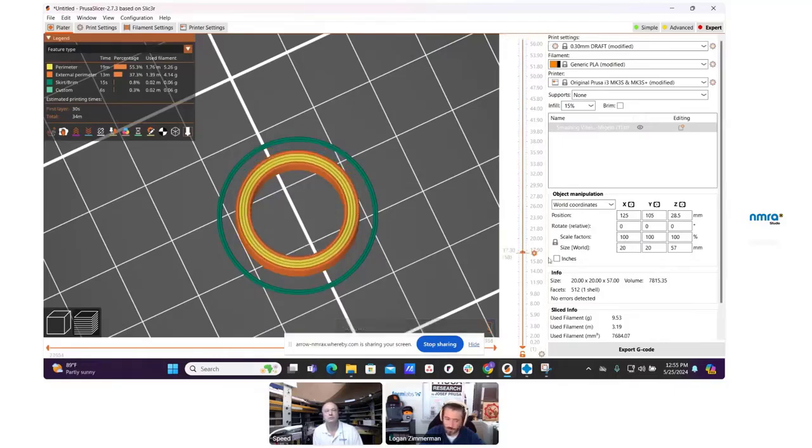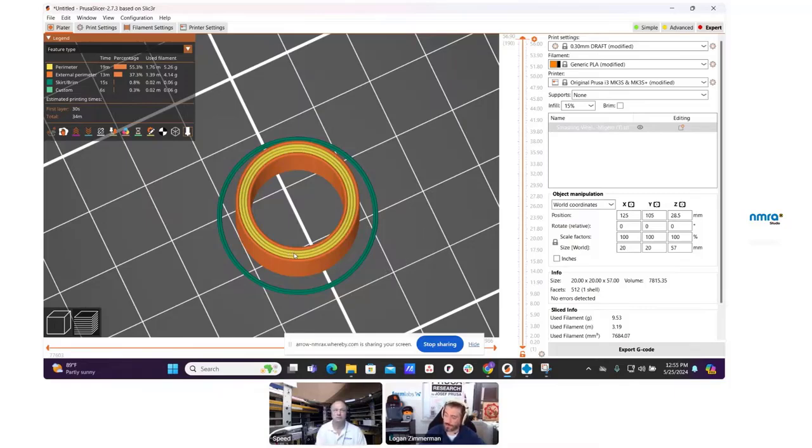Cool. So you can just design it so that feature has the 100%, and all the rest of the model is still hollow, still time friendly for printing. You don't have to waste all your plastic on 100% of the model, just the feature that you're struggling with.